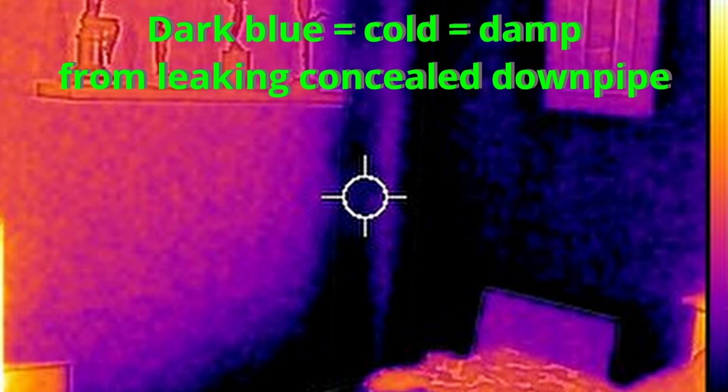Thermal imaging can be used, because anywhere that's damp will be colder than anywhere that's dry. So thermal imaging will show us where the cold spots are, and that can be a guide as well. And if you've got things like a boroscope or an endoscope, you can look through cracks and little gaps to get behind things. So those of us in the professions have the tools to enable us to investigate these things properly.